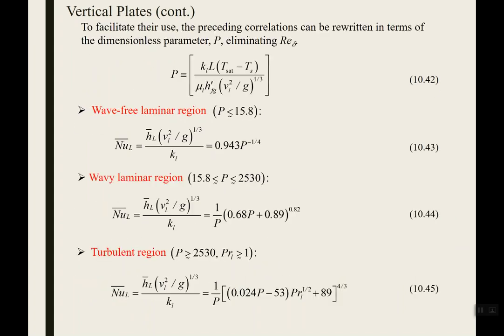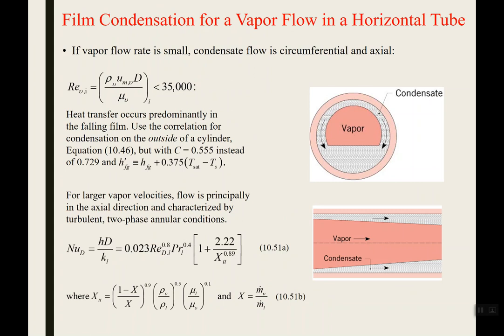Okay, I think I'm just going to stop there. So you do need to consider whether the flow is laminar or turbulent. There's a different correlation if you have horizontal flow or vapor flow in a horizontal tube. If you have condensation happening, here's your Nusselt number correlation, where you'd actually factor in the quality of your fluid, as in how much of it is a vapor versus how much of it is a liquid. And that's it. So this chapter, as in chapter 9, gets pretty hairy. I tend to find a really hard time asking exam questions based on this stuff. There may be a correlation that shows up. Who knows?